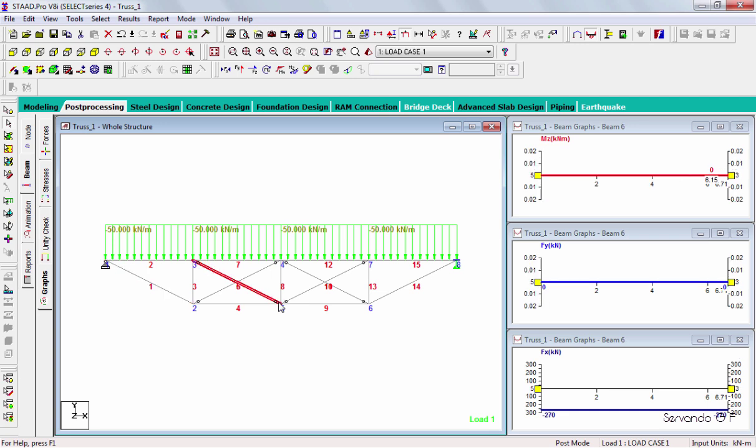Now it's okay. As you can see, it doesn't appear any bending moments, as it should be in any of these crosses, diagonals. So it's okay. So now if we check with the manual results, now we can be pretty sure that this model is accurate with the model that we wanted to design at the beginning.